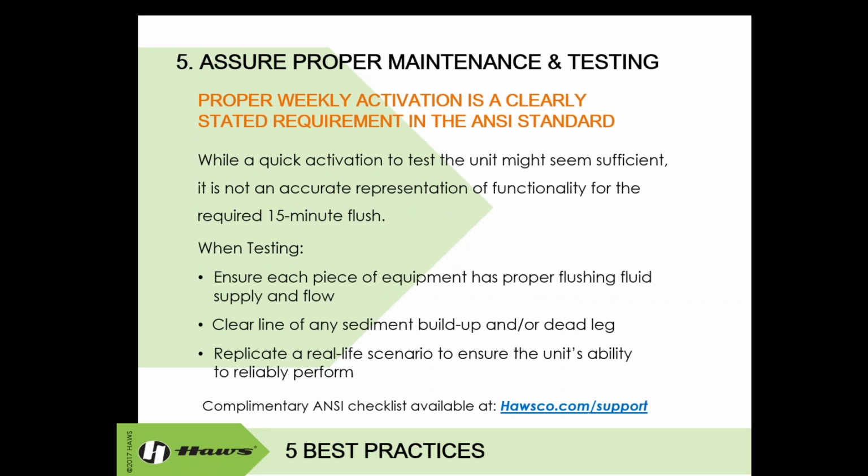And lastly, you want to ensure that you're doing the proper weekly activation. It is stated in the standard, and there are really only 2 requirements during the weekly activation. Number 1 is to flush the heads of the equipment, so the shower head and the eye face wash and/or eye wash head, long enough to ensure that water is getting to both of the heads. And then number 2 would be flushing it for a duration long enough to clear the dead leg, and the dead leg is any stagnant water that's been sitting in the piping.